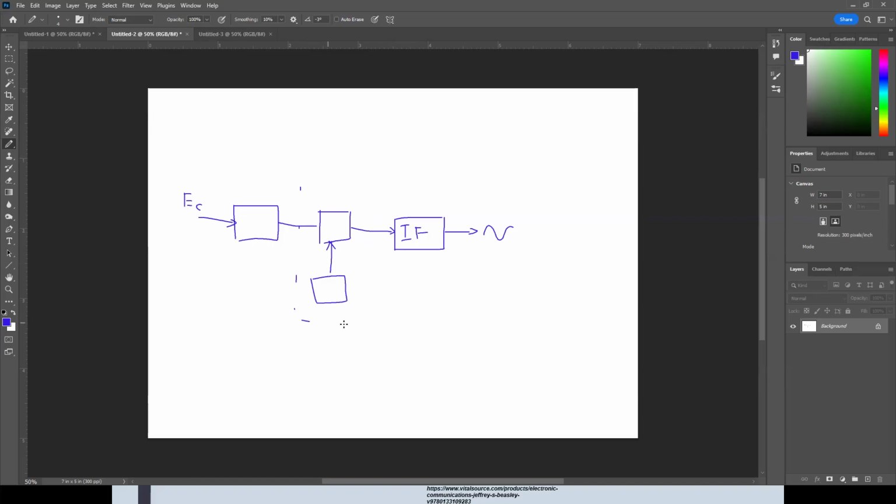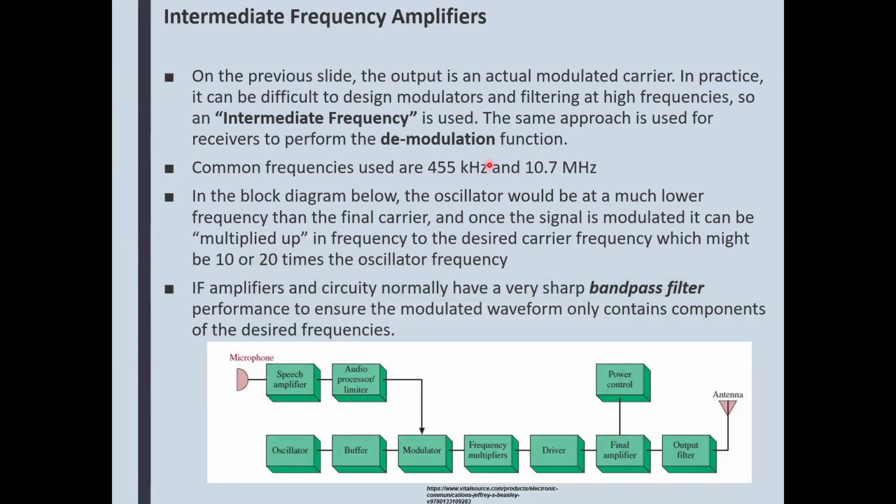At this stage right here, things are going to be converted to one and the same frequency, based on which we can dress up the electronic components and make this a quality receiver, because we just have to adjust everything to that carrier. So that carrier is converted to another carrier, and that carrier is being processed. The word superheterodyne comes to mind. Okay.